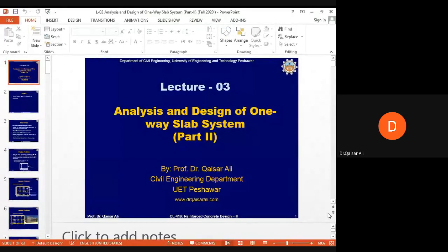By main reinforcement, you mean the flexure reinforcement, longitudinal bars. Yes. In the longitudinal bars, when a section was taken at the midspan of the beam, what did you see? The main bars were 4 and the hanger bars were 2. But the top bars were 2 bars.